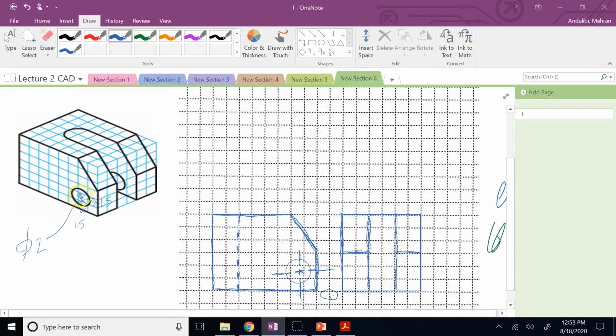Those circles you cannot see, diameters are 2, center is 1.5 above, so 1.5 above, 1 below, 2 unit diameter, so you can project them also horizontally and see that these guys are going to be what? Those 2 holes that I cannot see. They appear invisible to me, so I would draw them invisible.